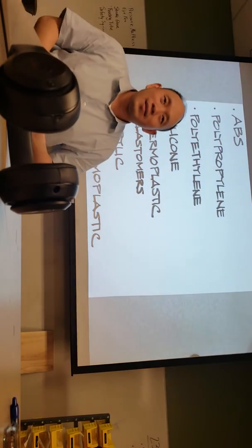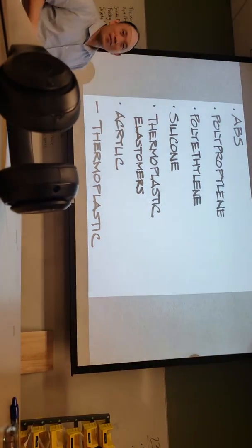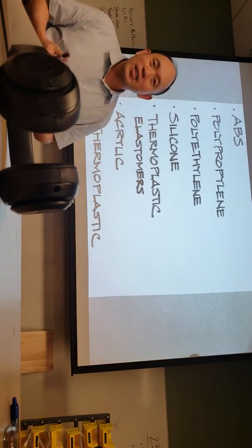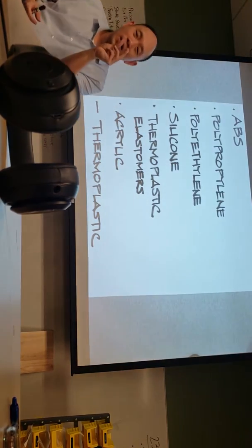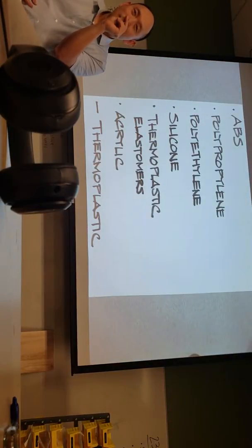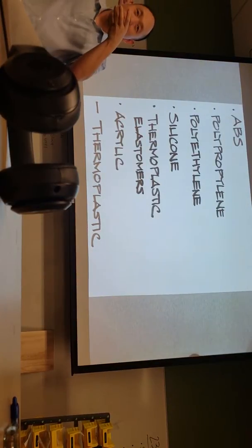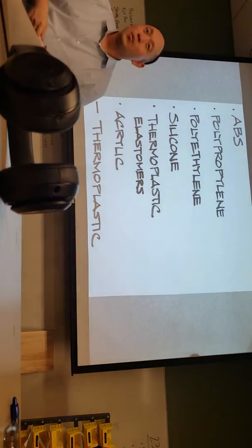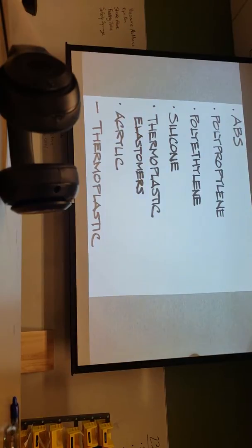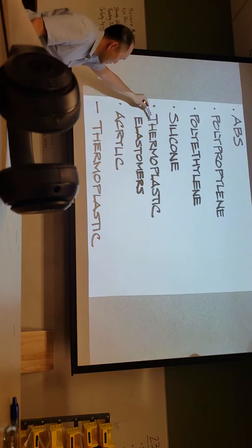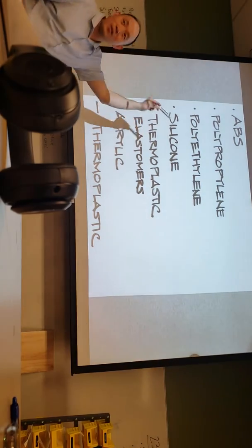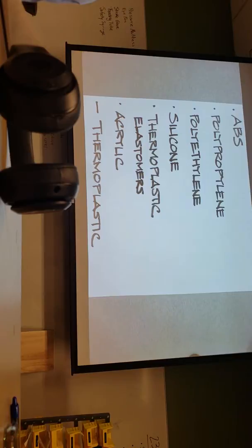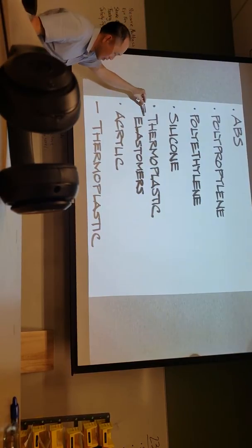The other related material is thermoplastic elastomers, or TPE. You've heard that term. That is a family name for a whole giant family of elastomers. And elastomers, sometimes you'll find on medical products, they're squishy, they're kind of rubbery, but when you let go, they basically spring back to their original shape. Those are types of thermoplastic elastomers. What exact type they are, you will have to do a little bit more research into this particular family to see. Sometimes it can be confused with silicone because they're both kind of bendy, squishy. So it's something to think about, maybe looking into both and seeing what works.